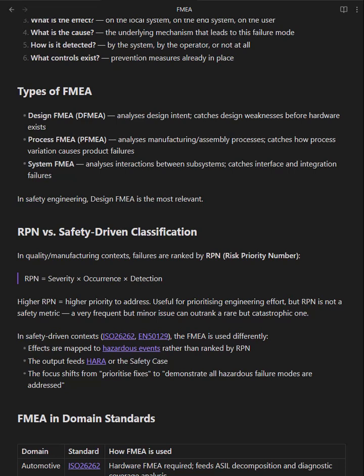Things that could lead to defects in the system based on elementary causes happening during assembly, like a loose screw or an inadequate type of assembly. Those elements we catch in the process FMEA.